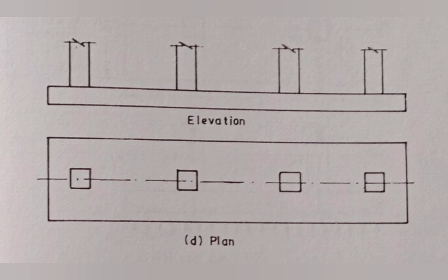Depending upon the center to center spacing of columns, loads on column and the bearing capacity of soil, the strip footing can be provided in the form of a slab of uniform thickness or in the form of a beam and slab type of construction.